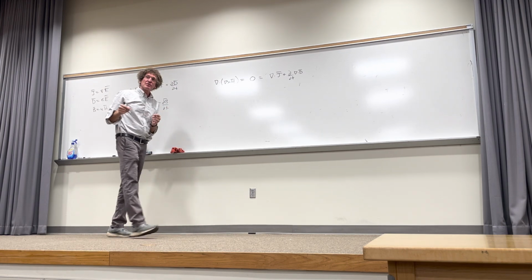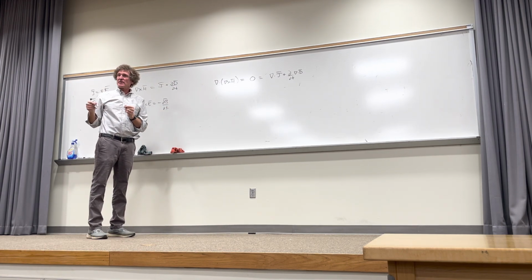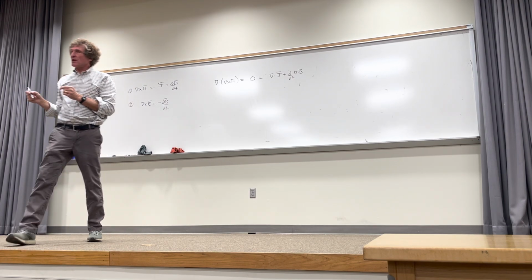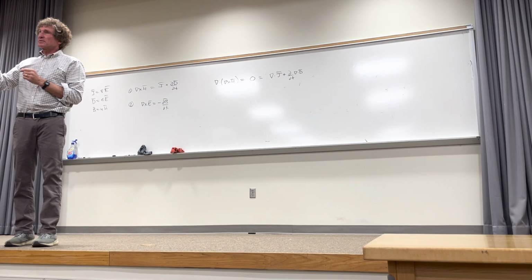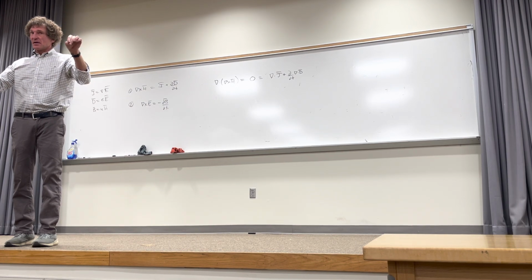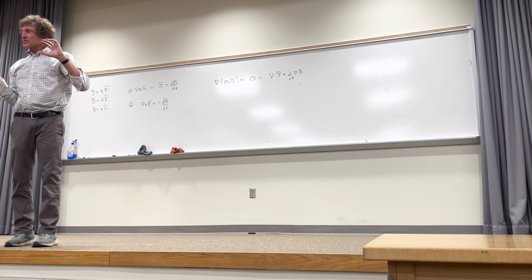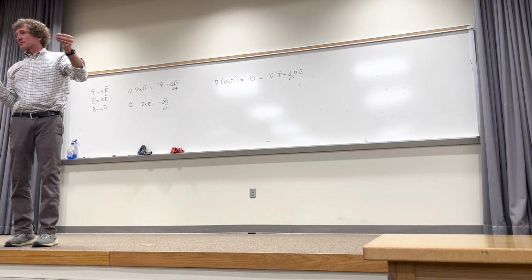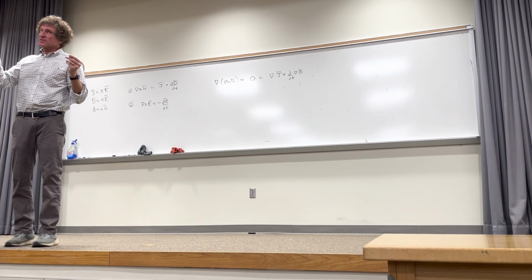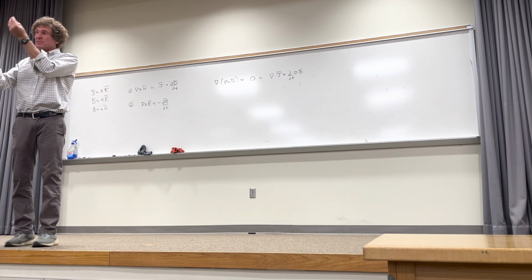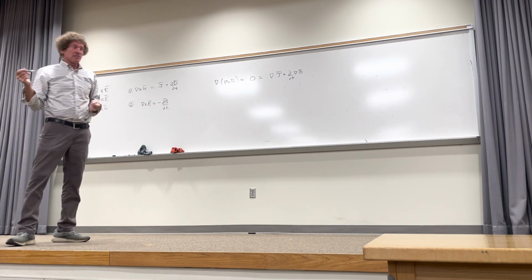This is called the continuity equation. Are you familiar with this equation at all? Have you heard of continuity? Well, you have, you just didn't know it. Remember Kirchhoff's current law? Whatever flows into a junction flows out of the junction, right? This one's slightly different. Whatever flows into the junction, which would be divergence of J, is no longer zero because this is time varying. It's equal to anything accumulated. With Kirchhoff's current law, whatever flows into the junction flows out, or results in a charge buildup, Q, and that would be a capacitive effect.